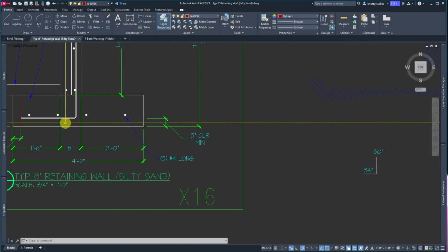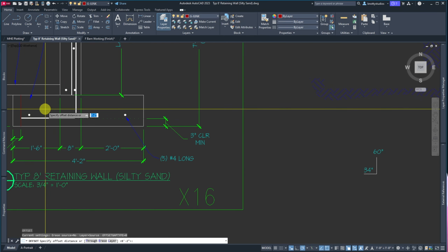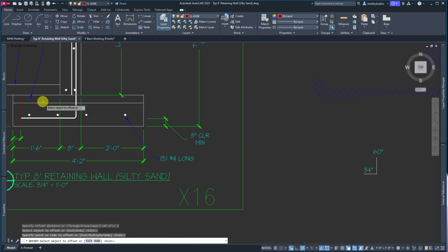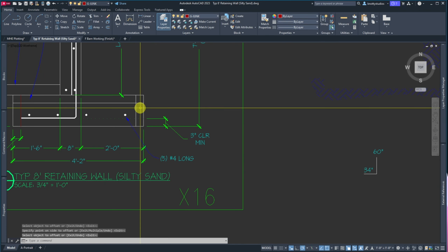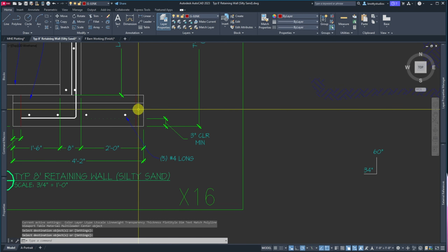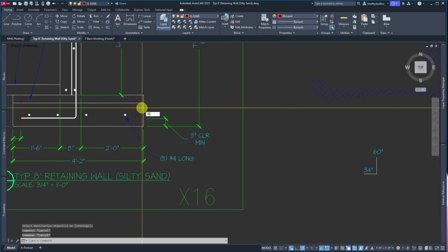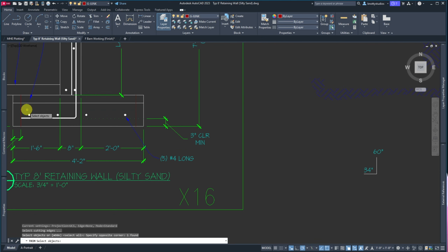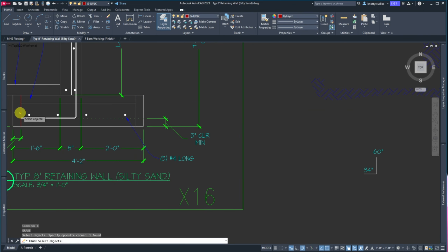And we had a transverse bar that we need up here, 3 inches down from here. So I'm going to offset 3. Now I'm going to offset 3 again here, just so you get this good practice. I would delete this so quick I wouldn't worry about it, but then it won't print if you forget it. So now I can trim it, trim that, there, and then I can get rid of these if I wanted to.